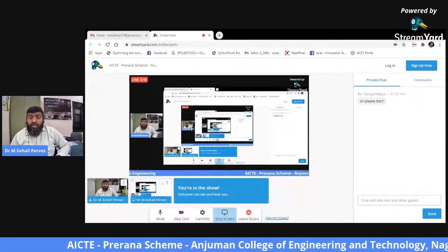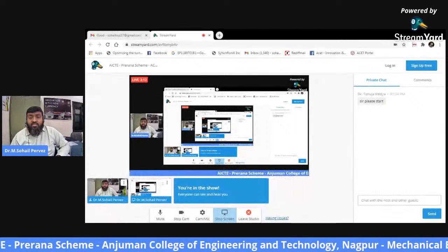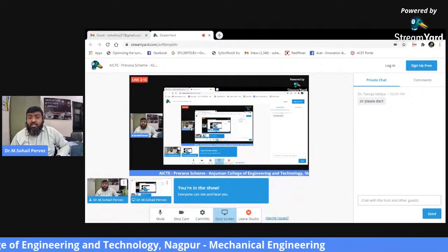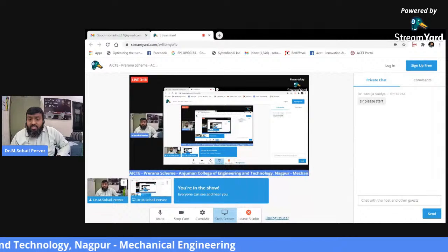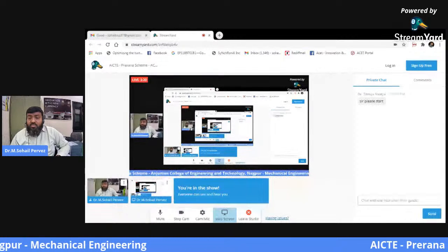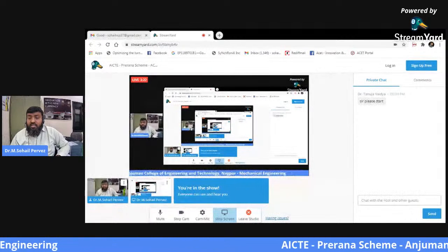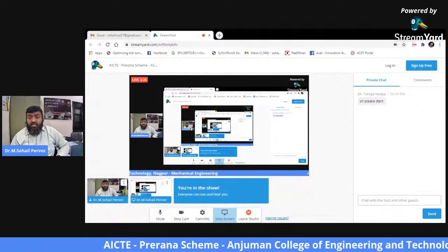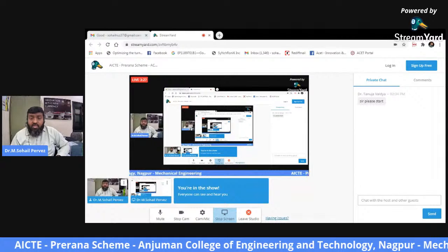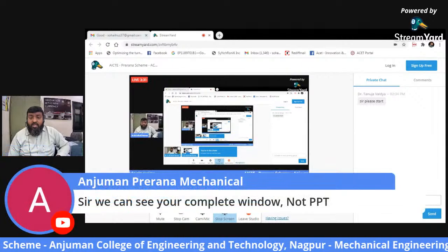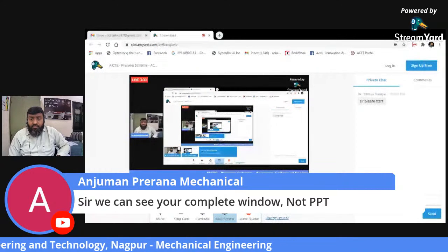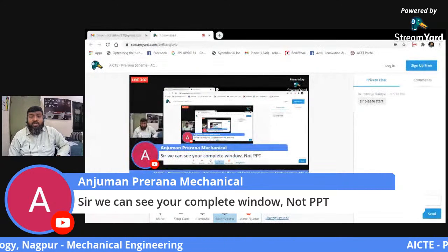Now, depending upon the basic criteria, stress is equal to load per unit area or force per unit area, we have written this equation as load is equal to throat area into allowable tensile stress, and this is for the single transverse fillet weld. Now the same can be used for double transverse, multiplied by 2. So this is the equation for single transverse and double transverse.